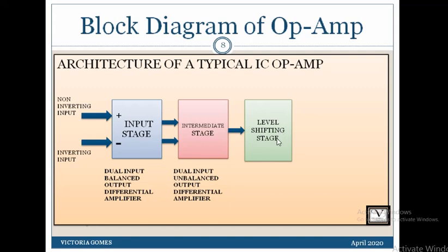As I said earlier, since large capacitors cannot be fabricated on a chip, the gain stages are directly coupled. Due to direct coupling between the intermediate stages, the base inputs successively rise up to such a high level that it requires shifting the input voltage level back to get an output level at which 0 output corresponds to 0 input. This is accomplished by a DC level shifter.